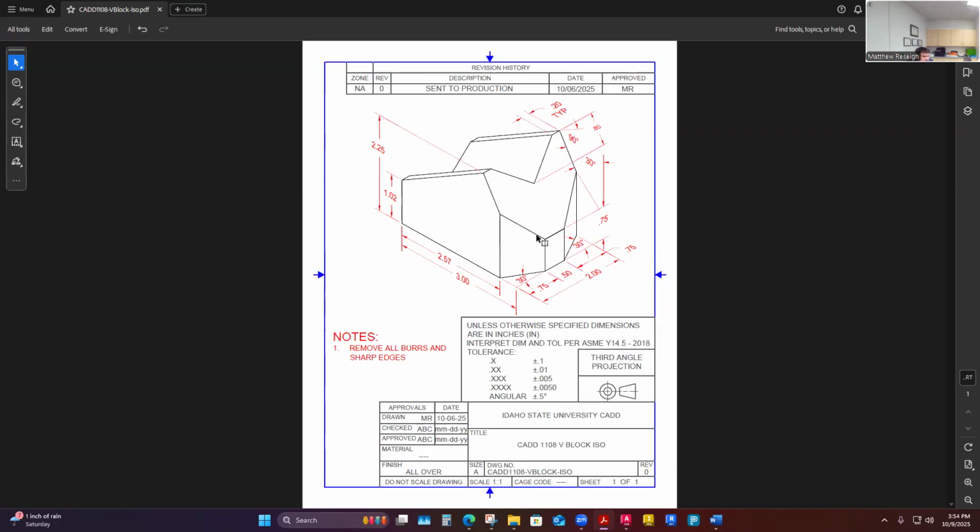This is a true length because my eyeballs are right on this surface. And this is going to be a true length, which I already have. But I'm going to get that side as well. So I end up being able to define the missing true length, which is the V's and this side. Yes, the V's and this side. I've already got the rest, but there's only one way to get those, and that's to do a projection plane off of here. And so that's what I'm going to do. Let's do it.